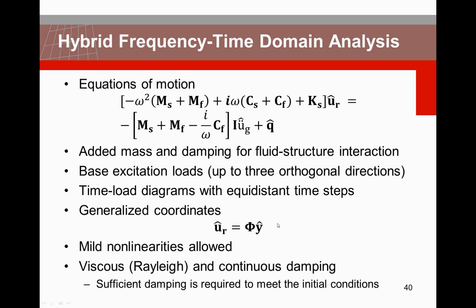This is also then the limitation of this hybrid frequency time domain analysis. The nonlinearities you can take into account must be local, which means that the mode shapes are not going to change during the analysis, because the method is based on these mode shapes.